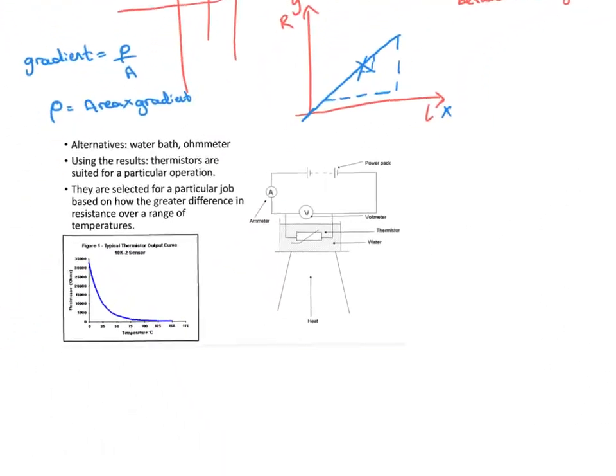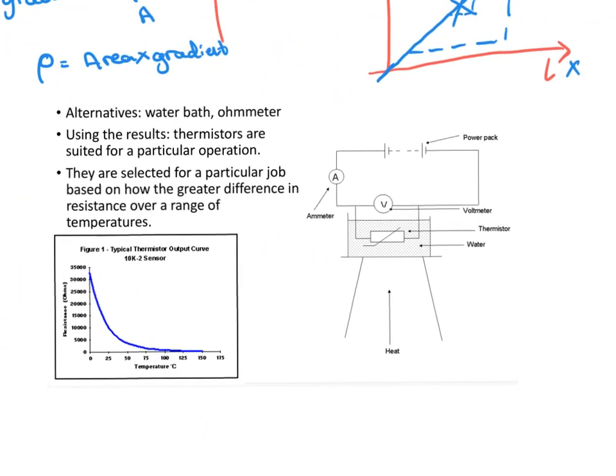And we did speak in the previous lesson about the experiment that you could do to figure out how resistance changes with temperature. We said that you need an ammeter, you need a voltmeter to measure the resistance, you need a thermometer, which is not shown here, to measure the temperature. So you should record the voltage and current, so potential difference and current, at equal time intervals, let's say every 5 degrees temperature change.